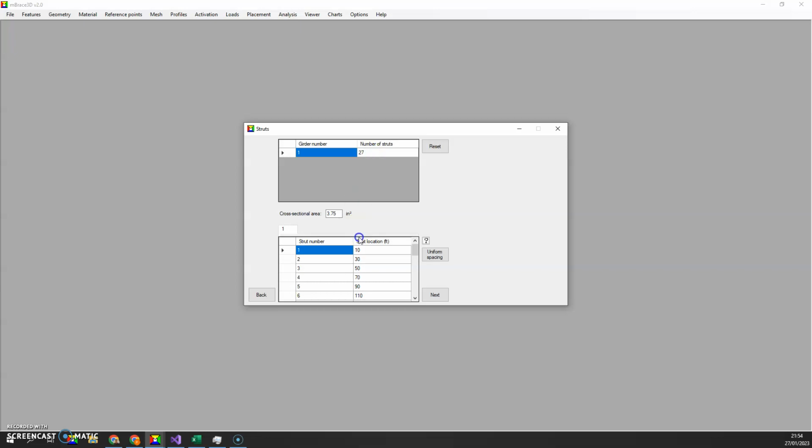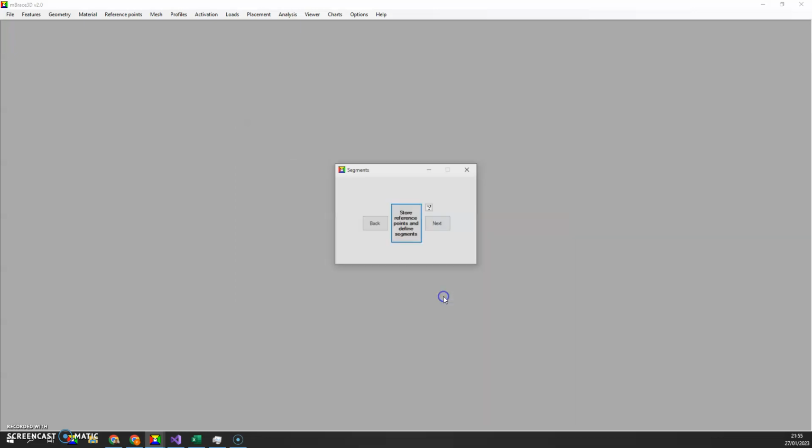We've got also 27 struts, which are just axial members, which are orthogonal to the tub, and because of their direction, they do not provide any stiffness against the cross-sectional distortion. So they are not very effective in preventing the twisting of the section, as we've seen in a previous tutorial on the Marseille Bridge, which tragically collapsed about 20 years ago.